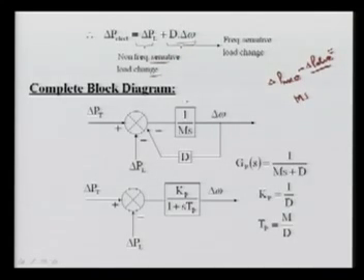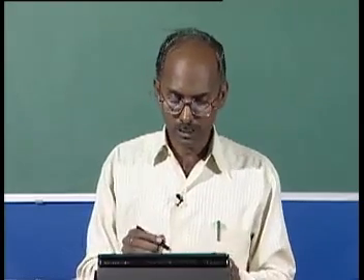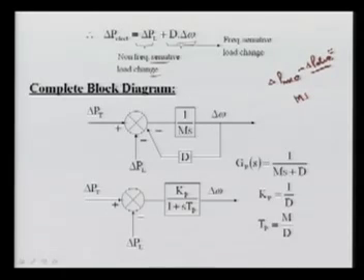So here, now I can include this complete model of generator plus load. So what we can do, this P electrical was changed, here this PT is your turbine power or T mechanical which I was mentioning. Now this PL here is a constant term, independent of frequency, minus again another term that is here adding with the frequency with minus sign. So this and this is now the total change in P electrical, and that is multiplied by 1 upon Ms, we are getting omega here. So you can say here it was giving you omega s, if you remember.